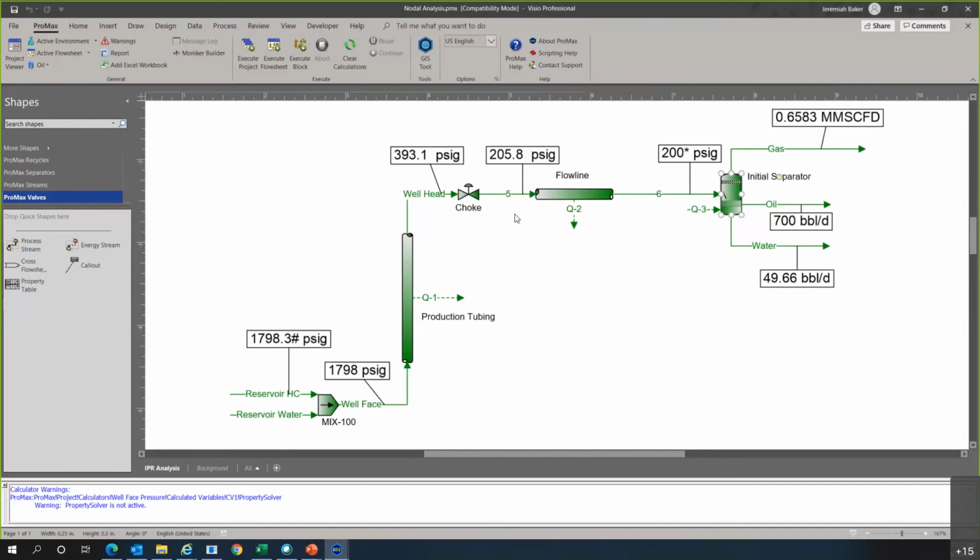be taking our choke valve out of the equation, and the way our separator runs, which is normally based off of our gas gathering operation, would then directly tie us to a flow rate, a production rate that we may or may not want to operate at. So chokes are normally a pretty good idea because it really helps us to be able to make decisions in different areas and make them separately from each other and not have unexpected outcomes. So that's one thing you need to consider too, is we can't just keep opening that valve and keep getting flow if we want to stay choked.